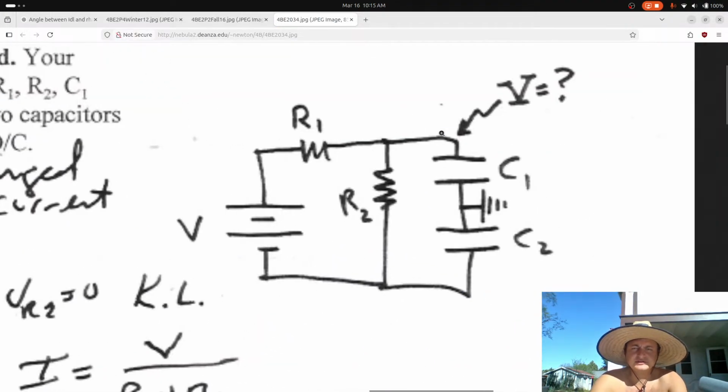Okay, so what do you do to solve this? So first, this is 0. But the thing is, there's going to be charge on these capacitors. Now the charge here and the charge here have to be the same. And this is just a property of capacitors in series, because this conductor initially started with 0 net charge. So even though there's charge separation, there's still 0 net charge. So then all the charge here has to be minus all the other charge here.